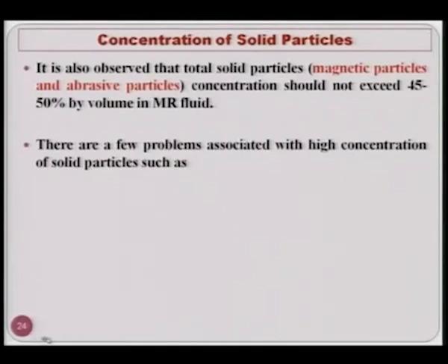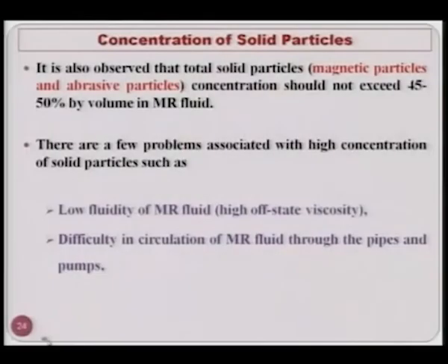There are a few problems associated with high concentration of solid particles, such as low fluidity of MR fluid, and also it leads to high off state viscosity. That means, when no magnetic field is applied, at that time viscosity is quite high, which is not good for easy flow of the medium. Difficulty in circulation of MR fluid through the pipes and pumps.